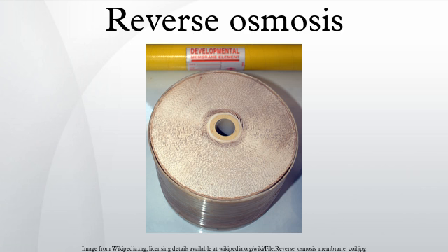CO3^2- + H3O+ = HCO3- + H2O, HCO3- + H3O+ = H2CO3 + H2O. Carbonic acid cannot combine with calcium to form calcium carbonate scale. Calcium carbonate scaling tendency is estimated using the Langelier saturation index. Adding too much sulfuric acid to control carbonate scales may result in calcium sulfate, barium sulfate, or strontium sulfate scale formation on the reverse osmosis membrane.